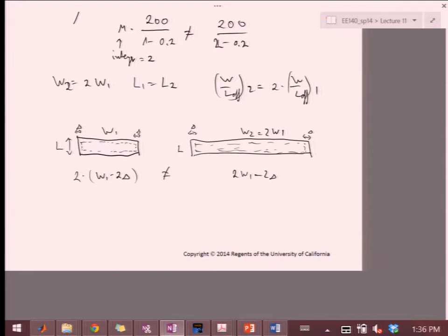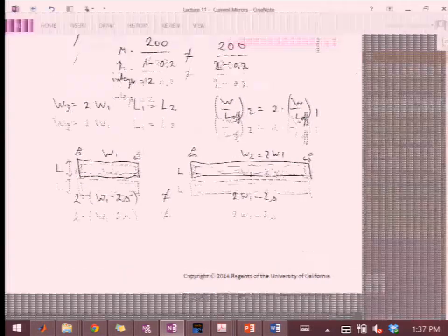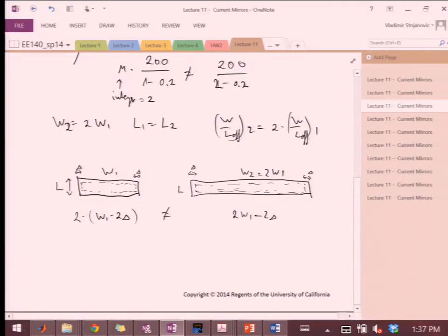You can play with the threshold, but that is a very expensive step. You have to dope differently and so on. You're a designer. You're supposed to take care of this, not the fab. Change what? That's still process. You're given a process, and you can only manipulate W's and L's. That's all, right? Even L in modern processes, and even W's in modern processes, you won't be able to do it. But what can you do?